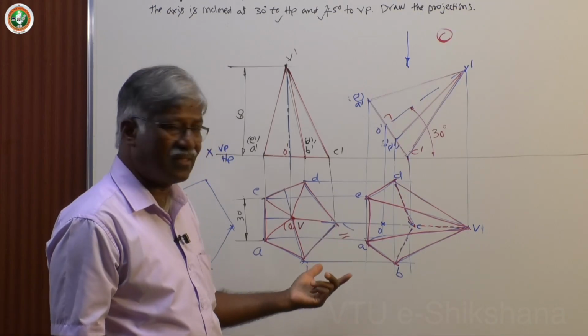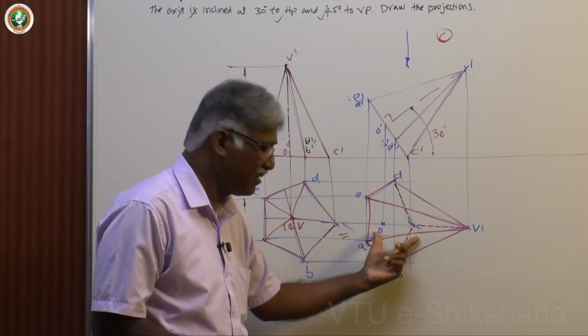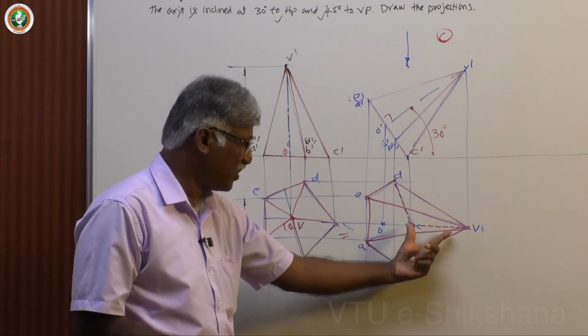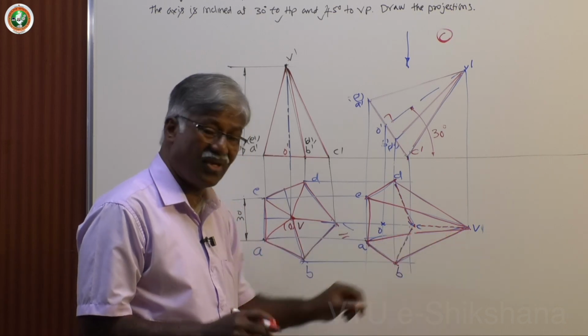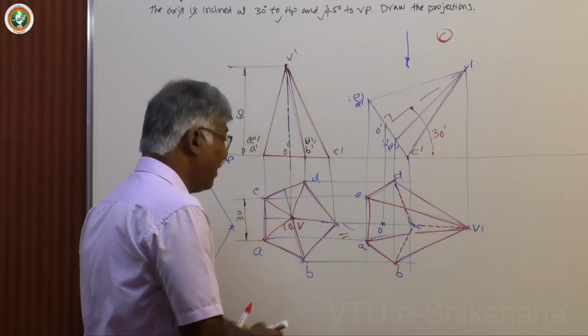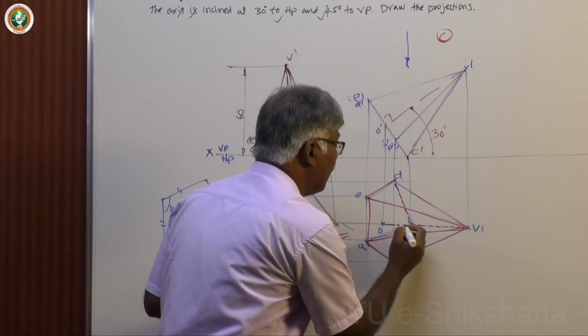Then what about the axis? There is little scope for axis representation here. Already the hidden line occupies this portion, and O to C you can mark, that is the only representation, by the full line hyphen full line hyphen.